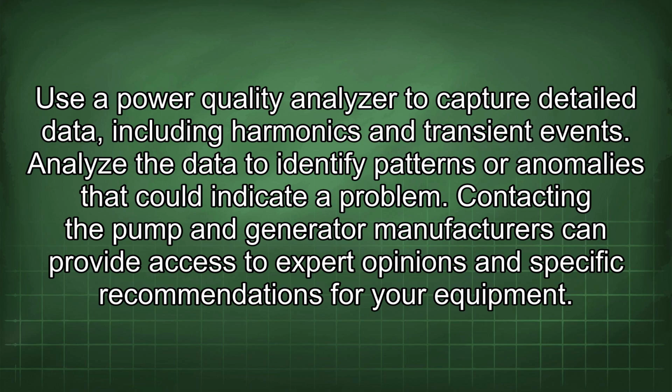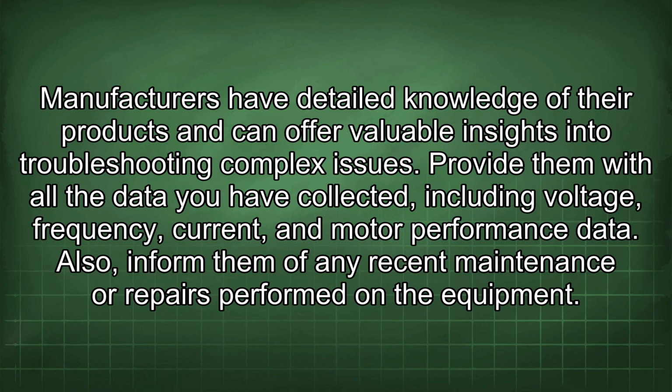Contacting the pump and generator manufacturers can provide access to expert opinions and specific recommendations for your equipment. Manufacturers have detailed knowledge of their products and can offer valuable insights into troubleshooting complex issues. Provide them with all the data you have collected, including voltage, frequency, current, and motor performance data. Also, inform them of any recent maintenance or repairs performed on the equipment.